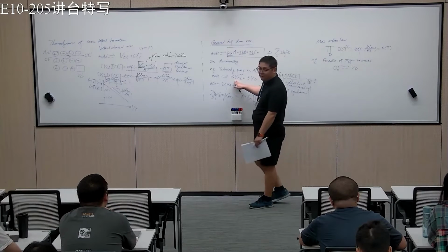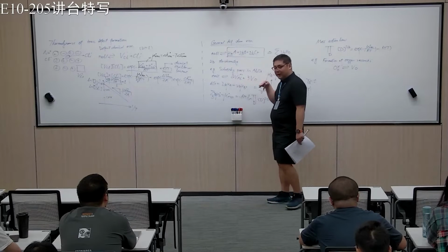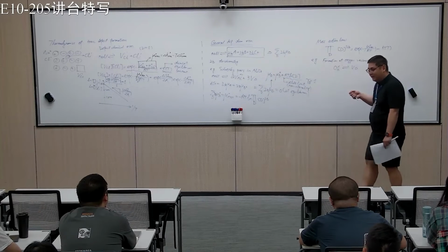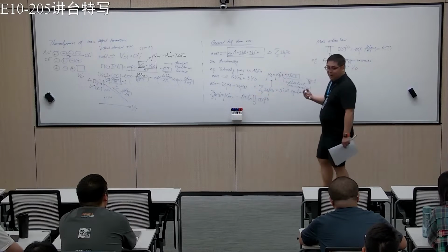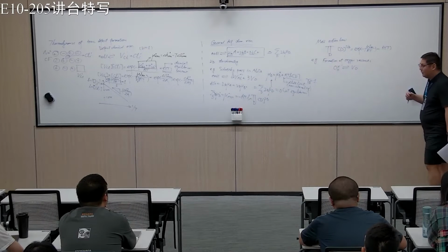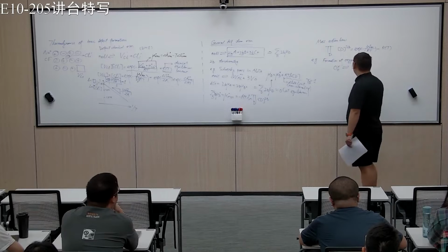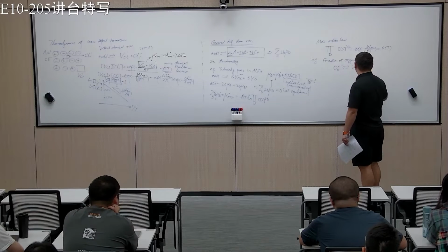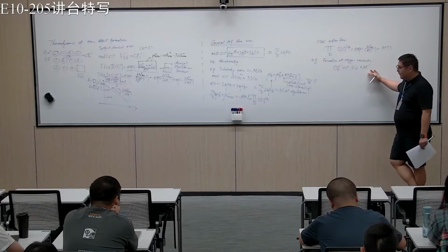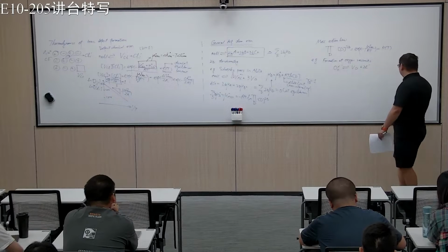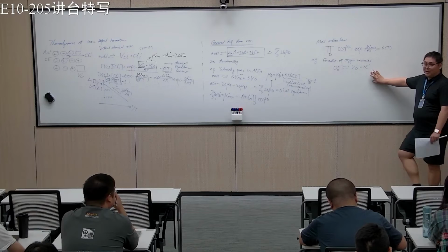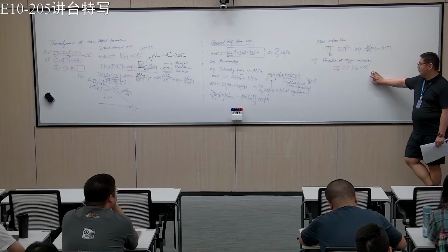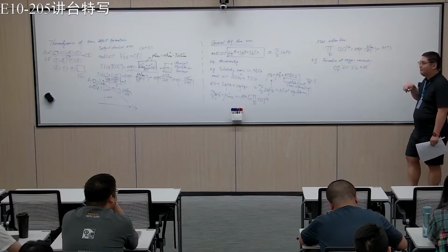So here we form aluminum vacancy, right? Which is the cation defects, and we have the negative charge. What if we do not want to form aluminum defect? We can form electronic defect. So this is basically electrons. So actually today the main topic will be electron defect. So we'll get to that part in a minute. I just want to write something like this. So basically this is just an electron, okay.